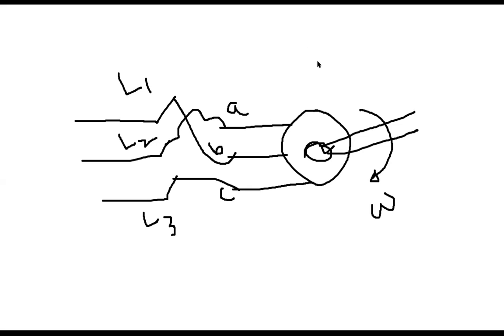So therefore, you might notice in lab number 3 or lab number 4, probably lab number 3, that at your first attempt, when you are making connection, the motor may not rotate in the indicated or recommended direction. At that time, immediately shut down the system and then just swap or interchange any of the two lines.